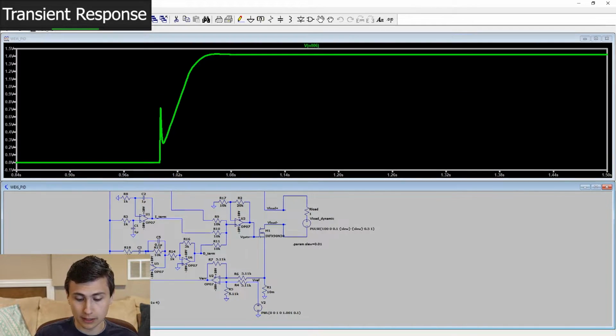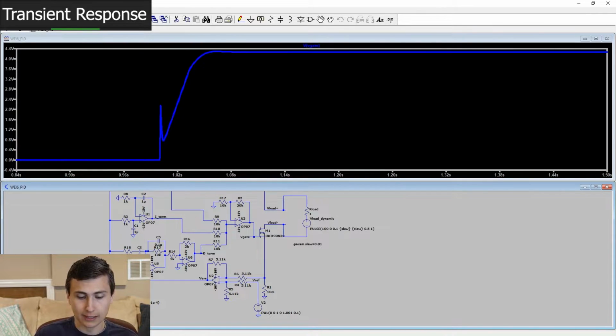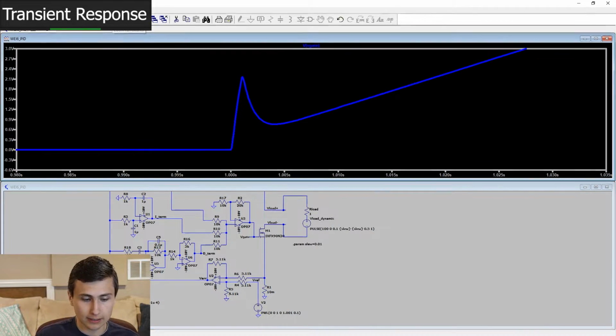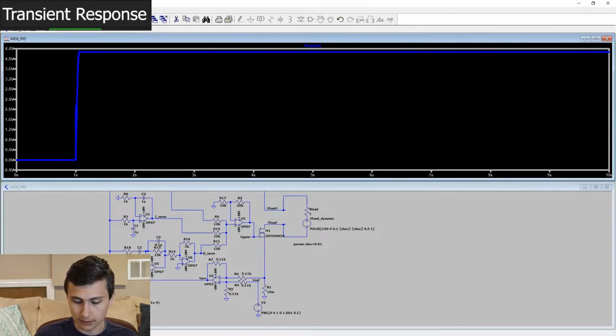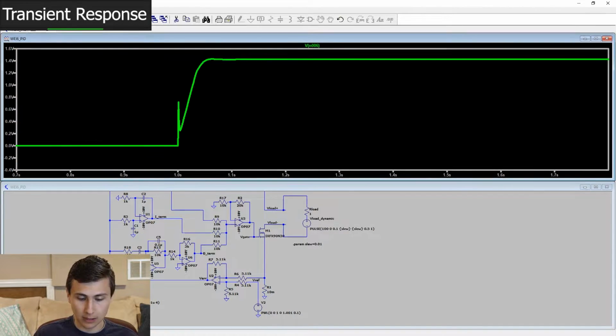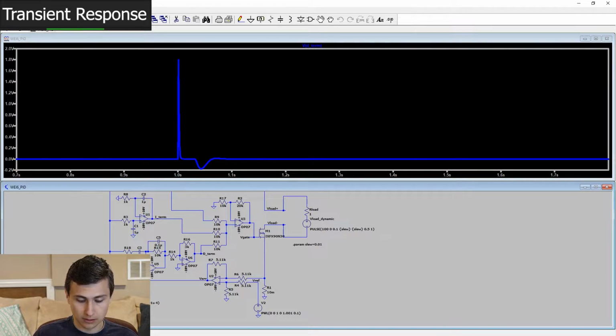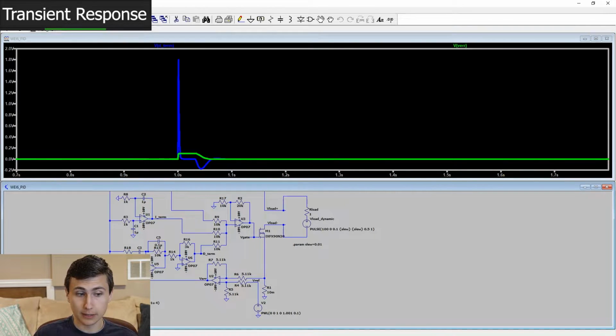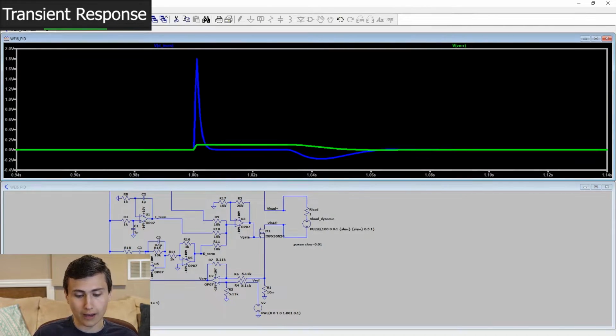that if we look at the summer, what's coming into the summer, and therefore out of the summer, it gets that big surge that kind of gets us up closer to where our MOSFET is enhanced, and the rest of the control loop kind of catches up in a moment. We can see the D term's response to the error term, right? The error term increases a bit. The D term says, whoa, now we need to get up there. But since it's filtered, it doesn't quite snap. It kind of gently moves. As we're held constant, that term comes back down to 0.